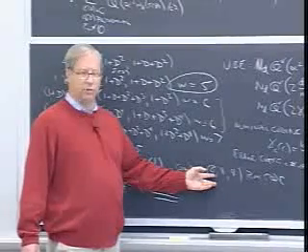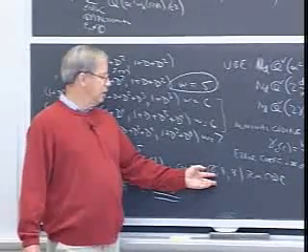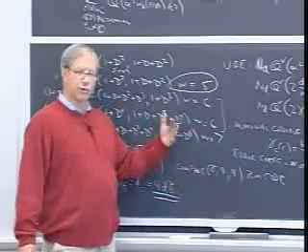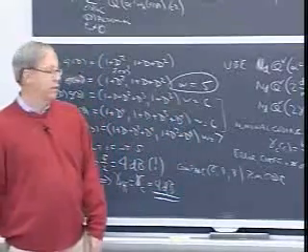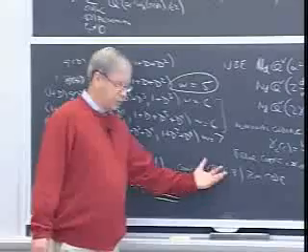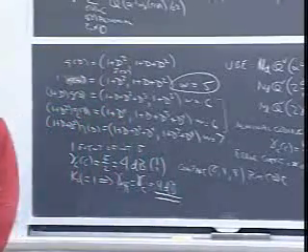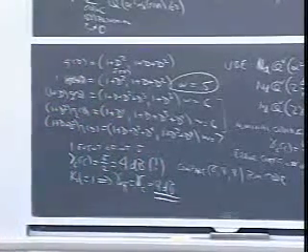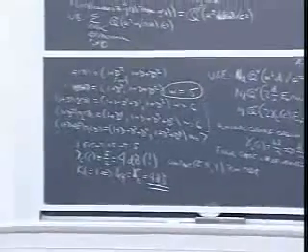We'll find for this code we can also decode it using the Viterbi algorithm with a 4-state decoder comparable to this one. So we'll be able to say for maximum likelihood decoding we have about the same complexity, but we simply get much better performance with the convolutional.